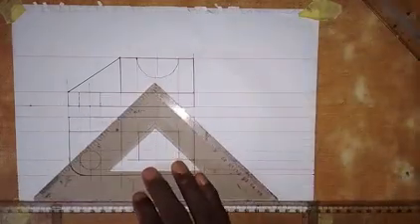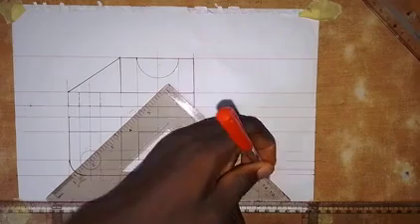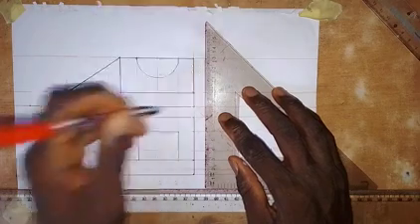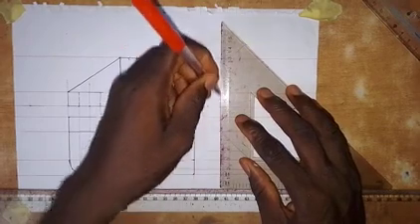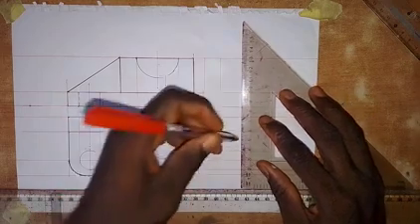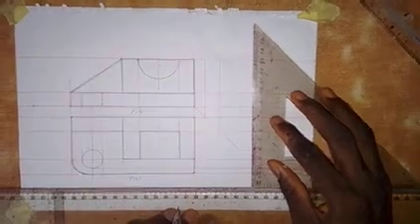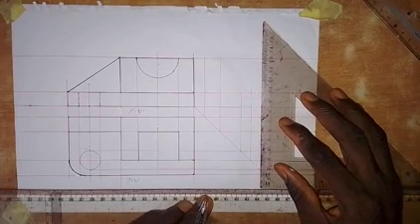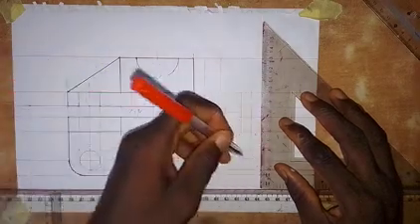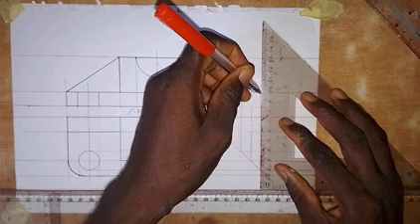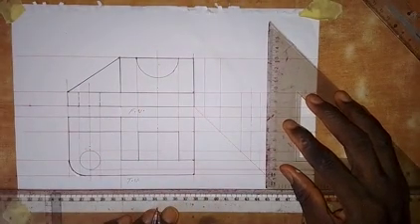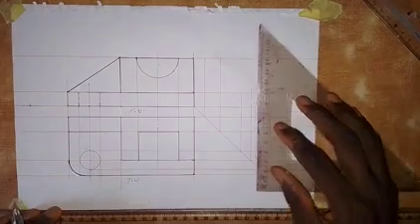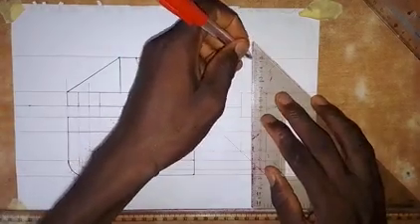So then with the set square at this point on the front elevation or the front view, we draw a line, and then from this point we are going to draw a vertical line here, okay, and also at this point we draw a vertical line like this. Then from this point, for the hole that is hidden, we draw a vertical line up, and this is the center line, so we also draw a vertical center line up here like this. And then at this point we draw a vertical line, okay, and then coming to this point, we draw a vertical line to this point, and then at this point that we have here, okay, alright, so this line has to go up like this.